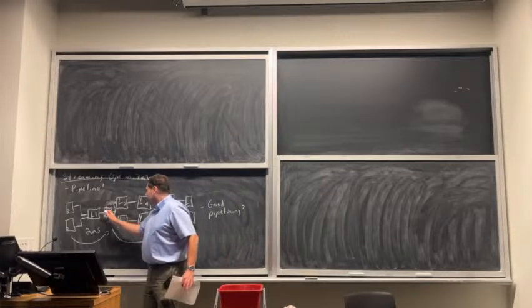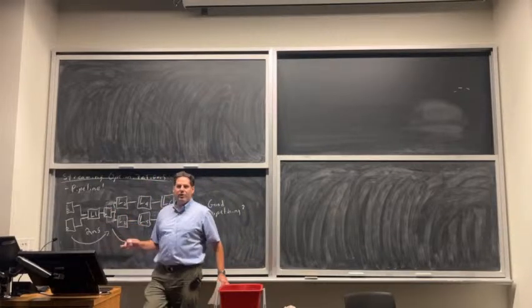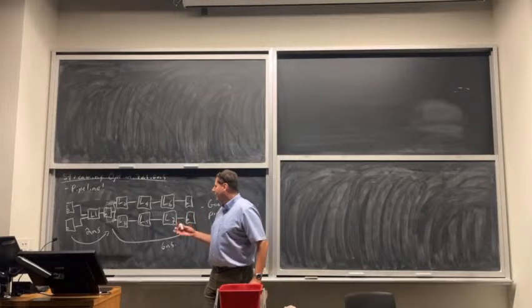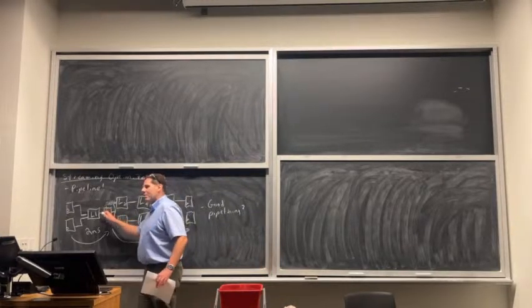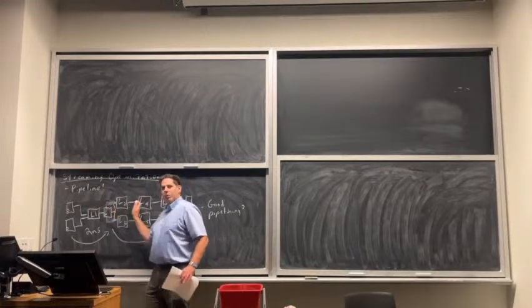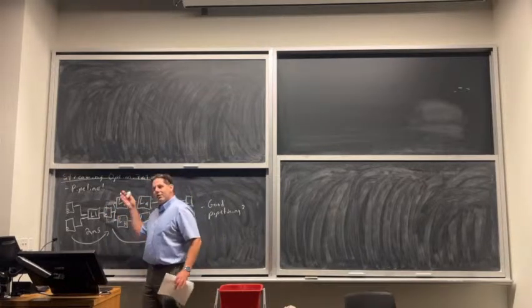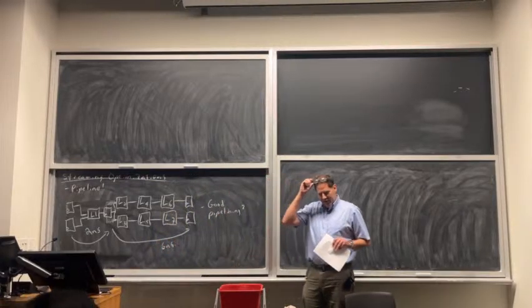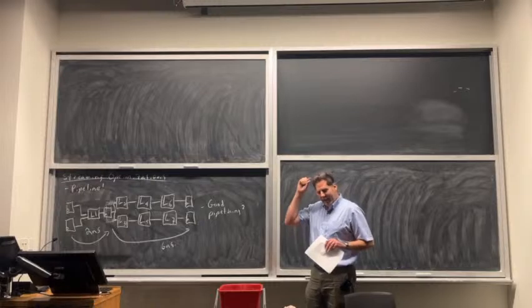However, CAD tools can move registers. Once you put them in, there is an automatic algorithm that can move them around. And when I say move them around, I don't mean move on the chip. I mean move where they are in your actual design netlist. Does anybody know what that algorithm is called? Maybe it's called retiming. Yeah, so it's called retiming.